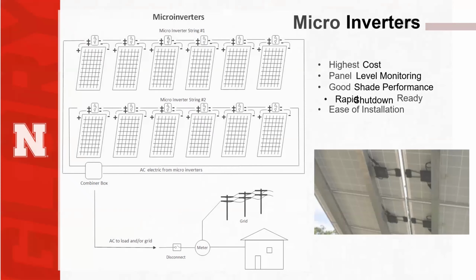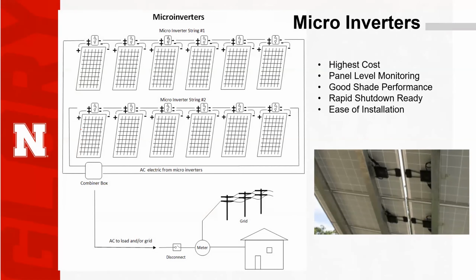So let's touch on microinverters now. Microinverters tend to work great because at the time of a power outage, the microinverters are communicating with the grid itself, and they're saying, oh, I don't see the grid. Shut off right up here, right at the roof level, right at the microinverter. And it meets that electric code in and of itself instantaneously. The code said within 30 seconds. I mean, it happens in less than a second. It's down and shut off. And so that works really well.